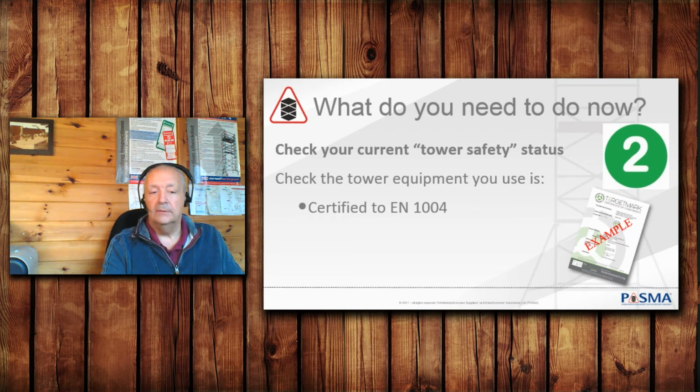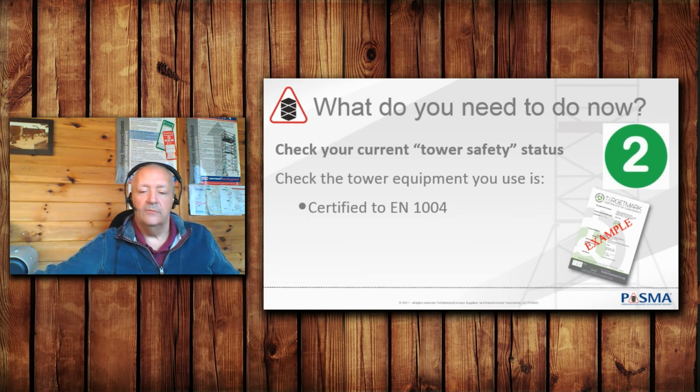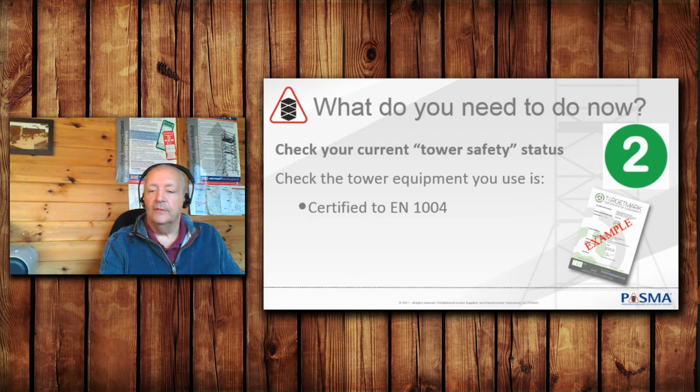If you hire a tower or use contractors, or you're a contractor who uses towers, same thing applies. Make sure that you specify it meets EN 1004 and check that any towers that you hire or that your contractors use are certified to EN 1004, and that you could prove this if required. And we're going to talk more about that later. If you have a tower, but you cannot establish and prove what standard it complies with, well, then unfortunately you need to assume the worst and get it replaced.